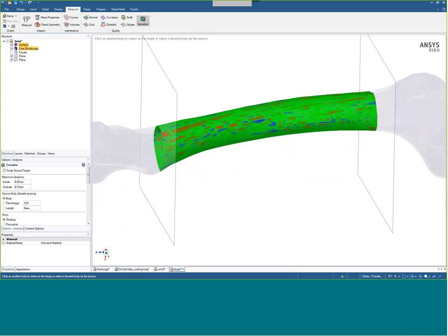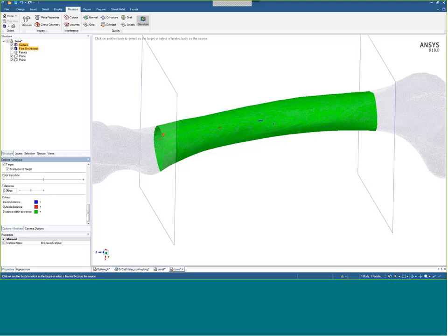And Justin has done some pretty interesting work, essentially unwrapping the STL and comparing the points that are on that flat part, mapping that to a surface, and then rewrapping that on the body. So it's a lot of complex algorithms going on behind the scenes to make it as close as possible to this design. And what shows us a little bit better is this tolerance. You might have a tolerance of 0.05 millimeters. That's crazy tiny. But you can see how close we actually are to that surface.